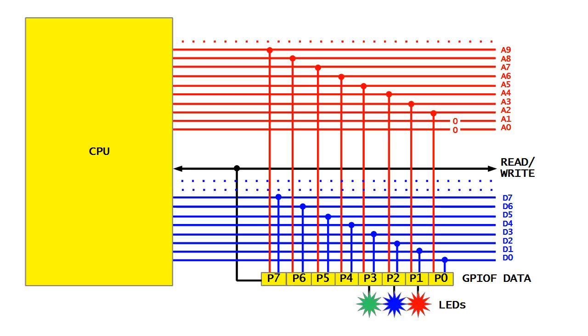Otherwise, the bit is unaffected, regardless of the value of the attached data line. For example, to isolate the 3 GPIO bits connected to the LEDs, you need to write to the address ending with 0000 111000 binary. Please note that the two lowest order address lines, A0 and A1, are not used, because the hardware requires all addresses to be divisible by 4.